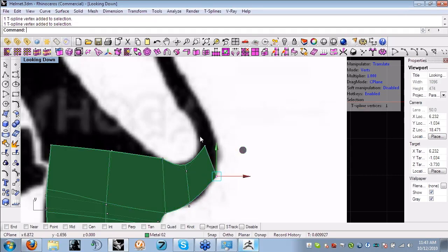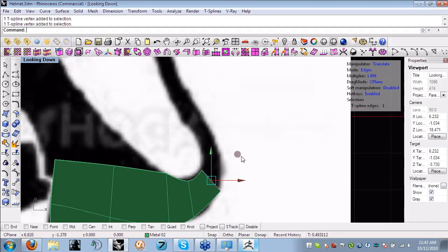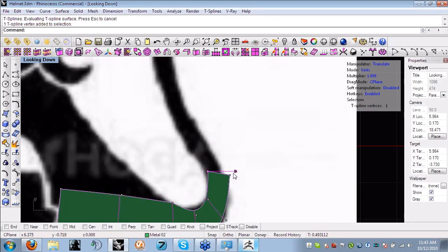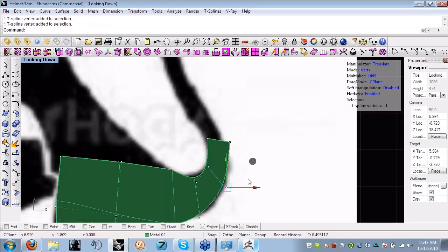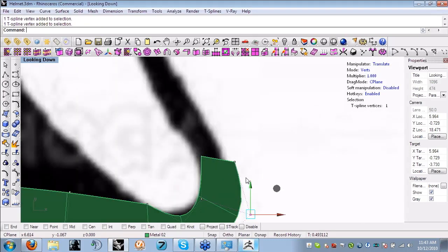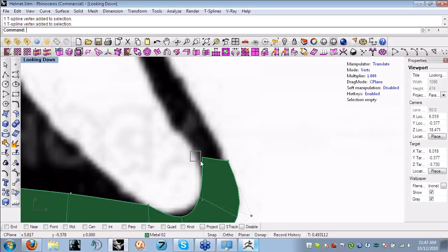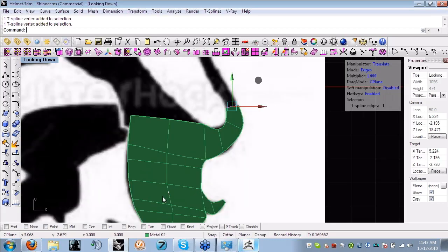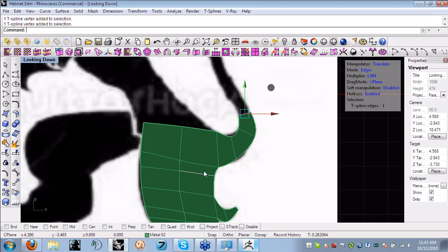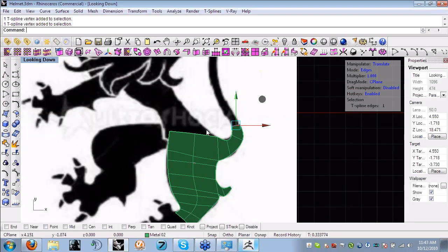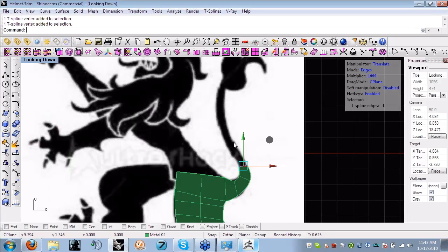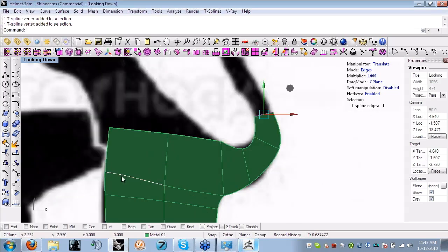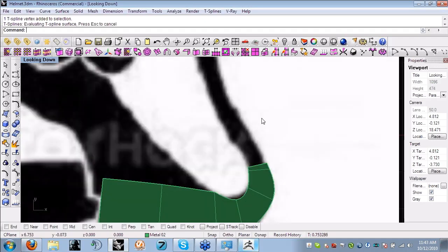And there's just another question that came in about how, when you're doing this with the line, if you just traced an outline and then thickened it, and the answer is no, you need to do a little bit more than just outline it. You are actually kind of creating the surface as you are pushing and pulling and extruding these faces. And the big thing too with the style of modeling is all of these little square and rectangle patches basically represent the topology of the model. And if I'm clicking and drawing with a curve, I may not get cross sections right here or UVs where I necessarily want them later on.